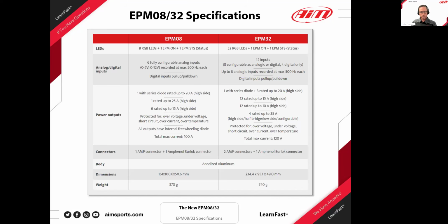a vehicle and you have to program them independently, and you have to remember which power outputs you're managing, because you're going to have to edit the configuration of that specific device. In the EPM's application, you don't need to manage them separately. They're all within one configuration, one home, one USB cable, and it simplifies the process quite a bit. And that's, of course, when you're mating up an EPM with an existing PDM.